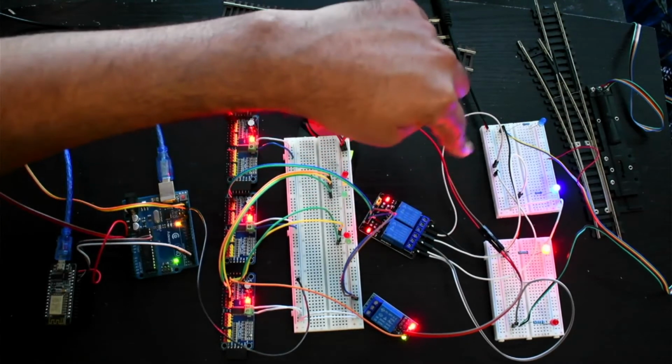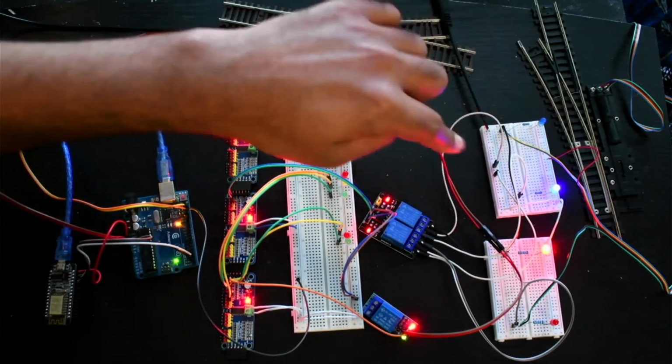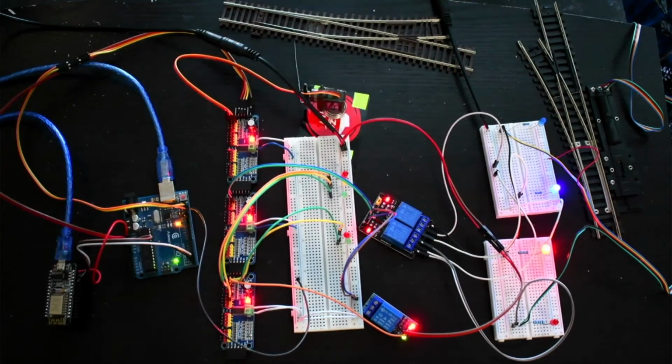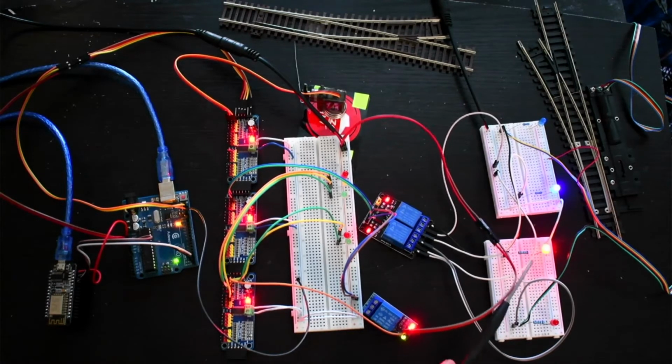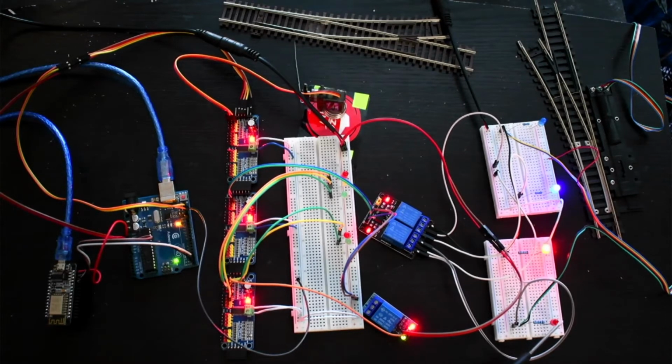And if you see, there are 2 LEDs connected here. So let me clarify this. Here you can see there is a gray wire and a white wire which carry signal for this LED and this LED. So the LED which is continuously glowing, you should never put your snap turnout towards that side. Always put it in the close position here.